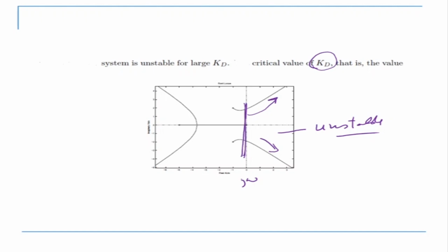So we should be very careful that when we are doing this kind of control of series elastic actuators, or when we are putting a stiffness element in between the actuator and the link, we have to be very careful which side we are taking the feedback from, and we have to ensure that it does not become unstable. Okay, now this is just to revise.